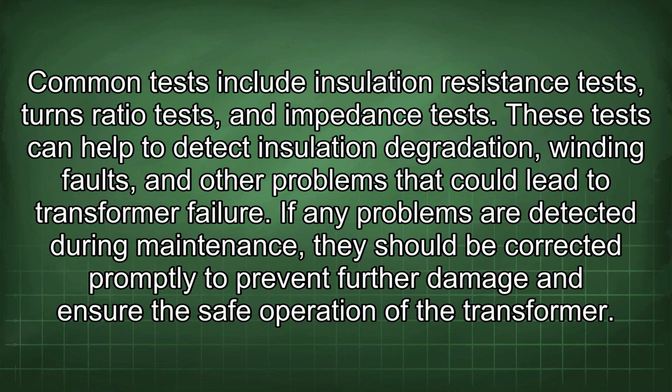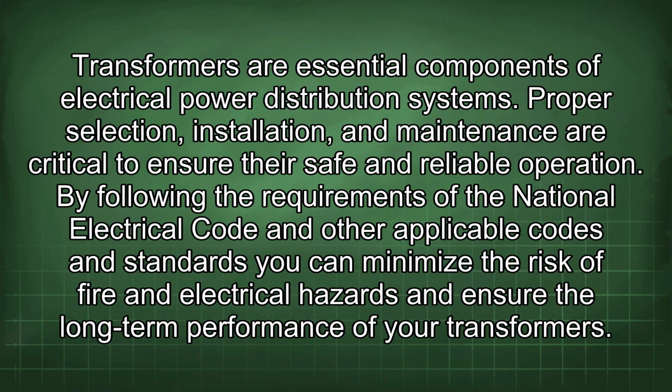Common tests include insulation resistance tests, turns ratio tests, and impedance tests. These tests can help to detect insulation degradation, winding faults, and other problems that could lead to transformer failure. If any problems are detected during maintenance, they should be corrected promptly to prevent further damage and ensure the safe operation of the transformer. Transformers are essential components of electrical power distribution systems.